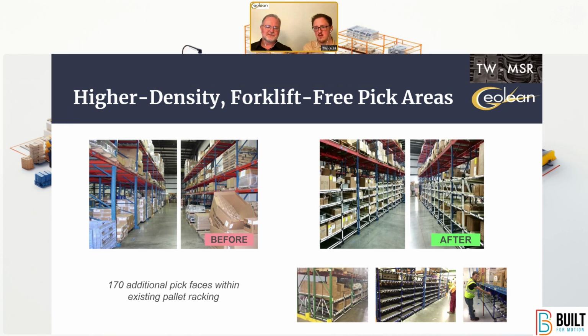And this is a particular example where space savings was the number one challenge. They needed more room in the warehouse. But we identified a lack of first in, first out. We identified some safety issues with forklifts and pedestrians in the same aisle, right? And by introducing something as simple as a gravity flow rack, we addressed that FIFO issue. We addressed the safety issue of materials flowing in one direction.